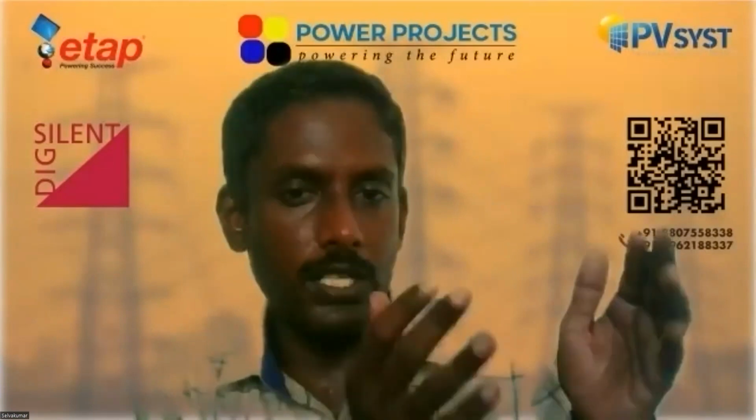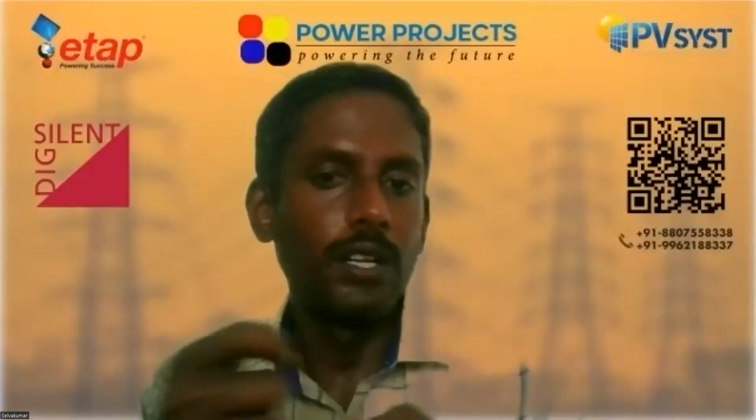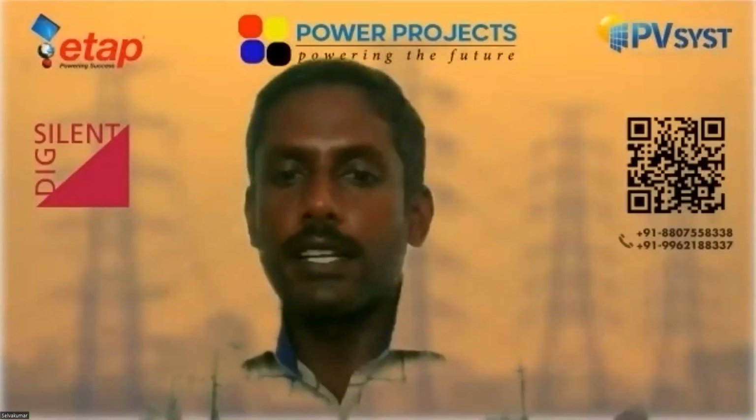Typically we use instrument transformers, that is, current transformers connected to the relay, to detect the fault by the current changing from load current to short circuit current. That's a huge change. Load current is like 500 amps, whereas the fault current is 10 kiloamps. So you will detect that as a fault.